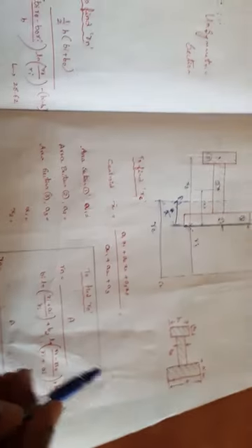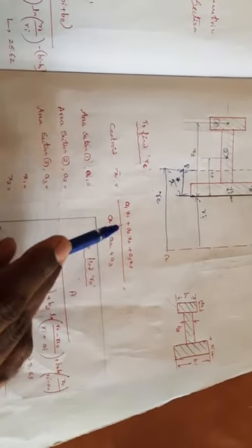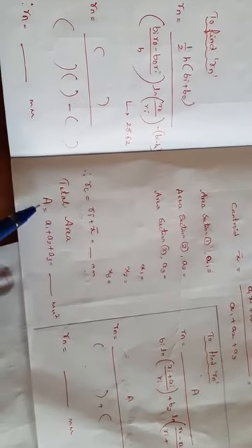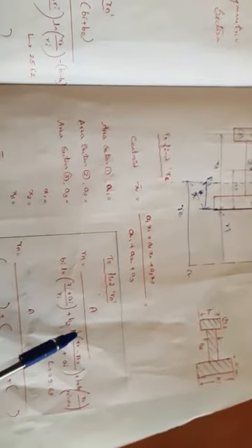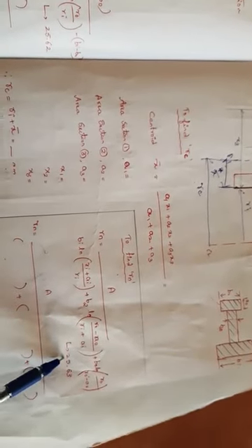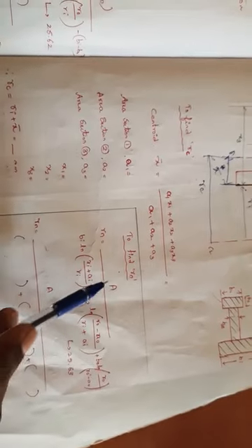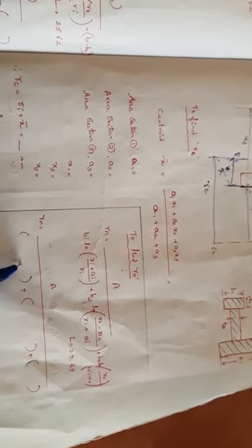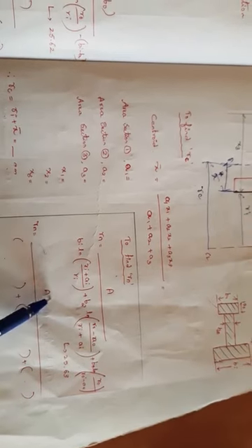Now to find Rn for the I section, first calculate the total area A1 plus A2 plus A3. Then we have this formula in the data book as equation 25.63. Substitute all these terms, simplify and add, then divide by the area, and we get Rn.